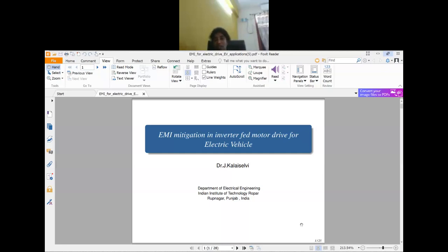In a three-phase inverter, the first, second and third phase legs have a 120-degree phase shift, so the high frequency sources also go through a phase shift. So the currents will automatically be different even if you have the same impedance across the phase legs. The sources would be different.